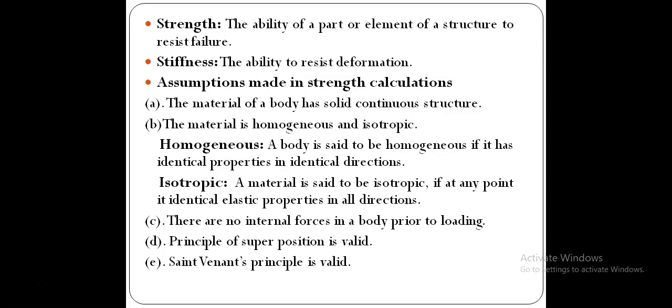Sometimes a material can carry only up to elastic state. So once it reaches that elastic limit, the material may fail. Like that we can fix the failure criteria for that particular material. For example, glass cannot go beyond the elastic limit. So depending on the material we can fix the failure criteria. Some other material we can go up to ultimate state or breaking state, like steel. So the failure can be fixed at that level, either ultimate or breaking level.